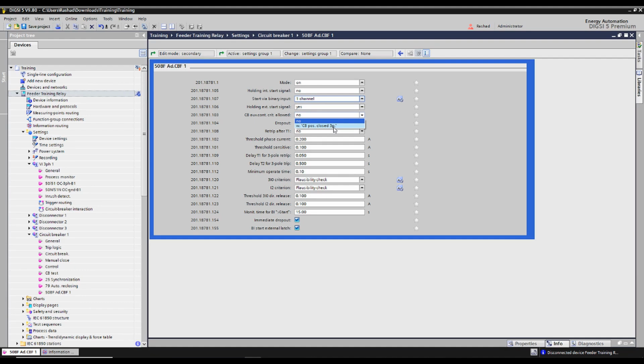However, having a protection function like oil low level active is very dangerous. Why? Because it means that the winding is without insulation, which could later lead to a complete breakdown. In this case, if I rely on the current reading, I won't know whether the breaker is closed or not. On the contrary, I would think the breaker is open because the current is low. In this situation, I must rely on the state of the breaker.